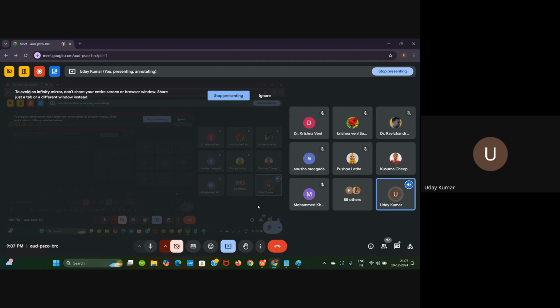So what we have done, we have added some buffers, and we have tried to clear that hold. And for setup, we tried to swap the cells to LVT. Finally, what happened? Everything was fixed. Everything was fine, but power blew up at the end. There was a lot of leakage power. So then we came up with a very unique methodology called TPS methodology.